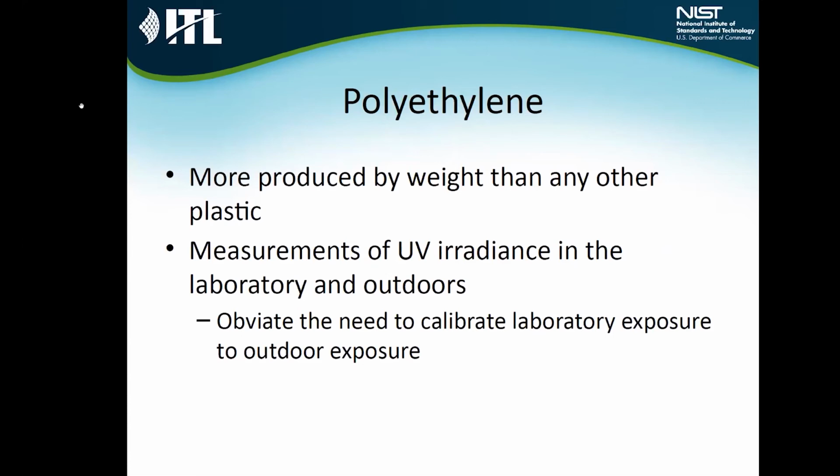And we made another tweak to the tactics. Again, not the strategy, same strategy, but the tweak we made for the tactics was to measure UV exposure both on the sphere, which was done anyway, but also measuring as best we could UV exposure on the samples that were weathered outdoors. And the thought was that this would remove the need to calibrate, that the calibration factor had to do with UV exposure, in that UV exposure on the sphere was much more intense than UV exposure outdoors.